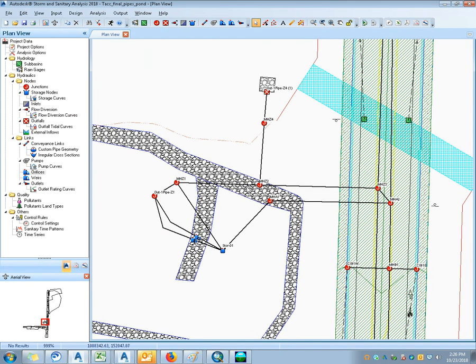What you'll be able to tell there is where we were a few years ago, where the wish was to go into existing detention ponds and rework them to save the fish in the stream and such. Totally. And what we needed to do, and what we did do, was run the old drainage single event model through them. And it showed it was backing way up in the pipe upstream. Exactly. That was tedious, but it's quick with this method. Yeah, this is quick. And I was saying how annoying it was earlier, but I did all this in like an hour or two. So it's not really that bad.